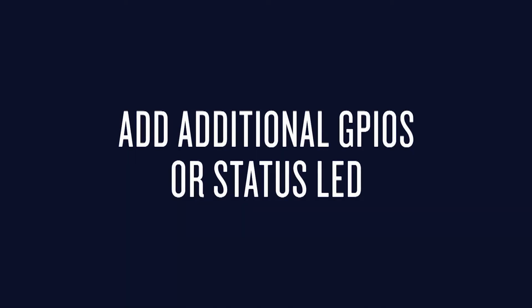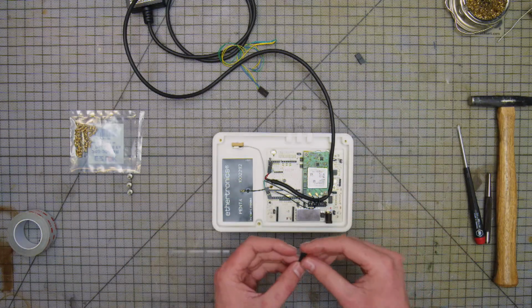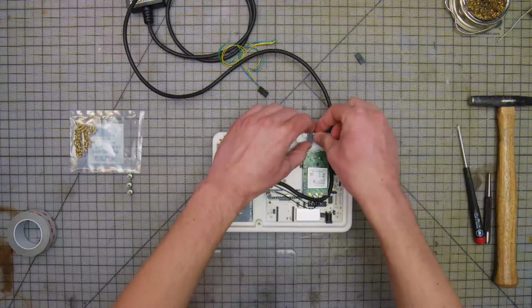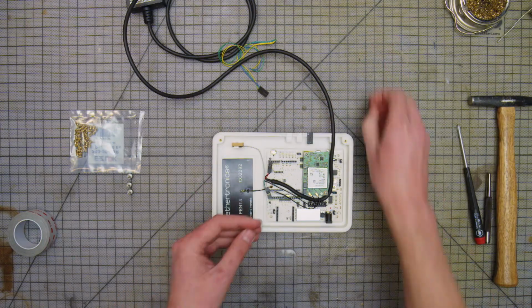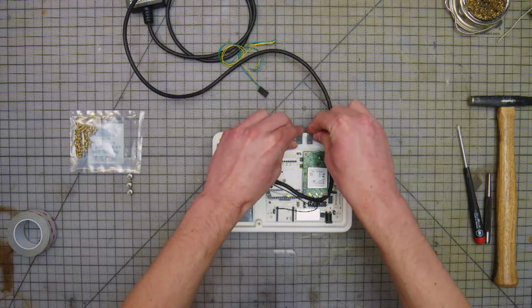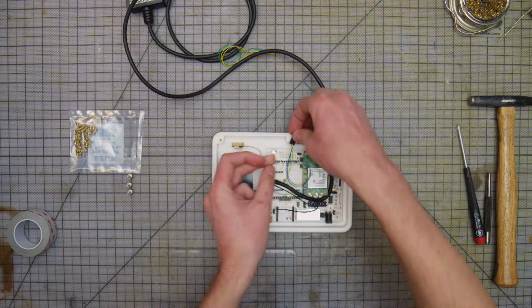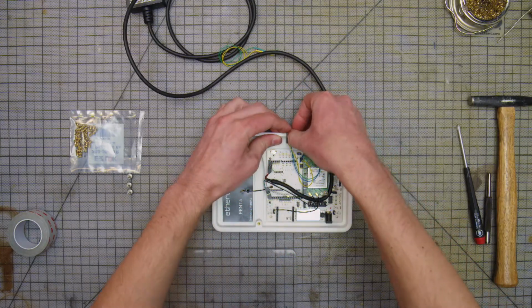In addition to wiring the Freematics unit to the breakout board, we can add several ports for additional GPIO function. There are 3 bosses at the top of the enclosure that are designed to accommodate 3-pin Molex C-grid connectors. The plastic housing can be glued in place for any wiring configuration of your choosing. The top of the enclosure also has the ability to accommodate a status LED.